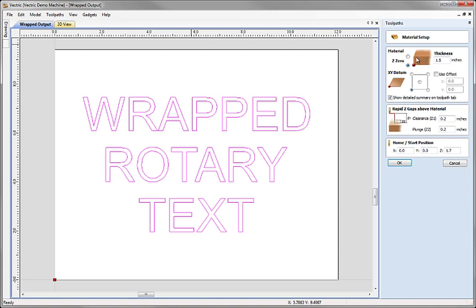That represents the fact that we've set this in the middle or the center of our cylinder. So you can imagine that 1.5 inch of material being wrapped around the center of the part where our 0 is. XY datum is in the lower left, so that's going to be down to the left hand side of our cylinder, and we'll pick that position obviously on the edge for X0, and then the Y0 will be whatever you want the starting point to be around the rotary or the circumference of the circle of the cylinder. Next we've got our rapid value set here, and the home position needs to be larger because we're working from the bottom of the block than the thickness of the material, so 1.7 is safe. I'm going to hit OK.